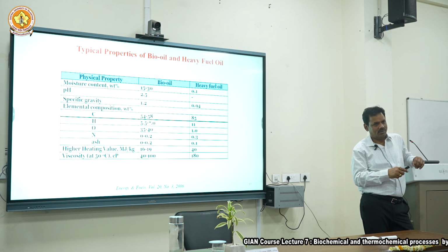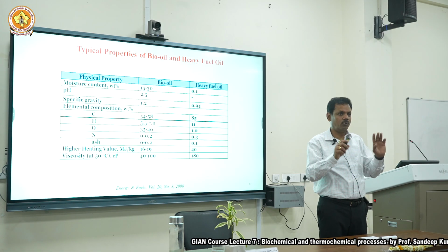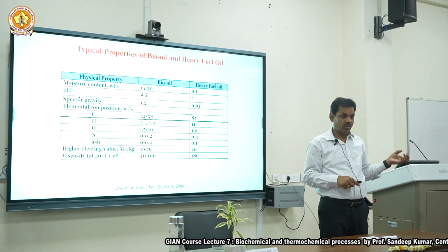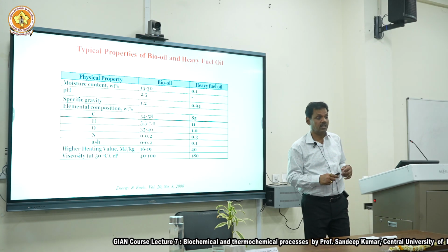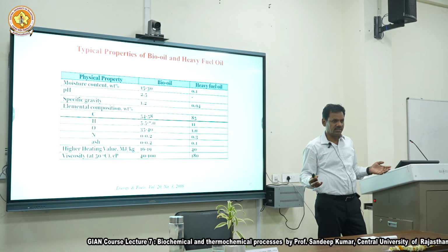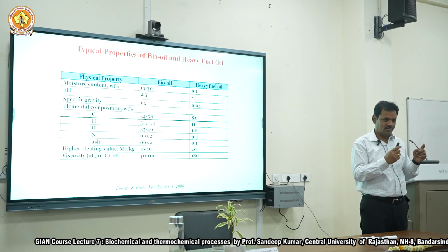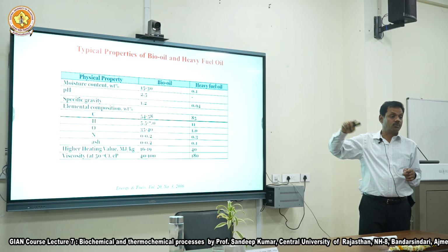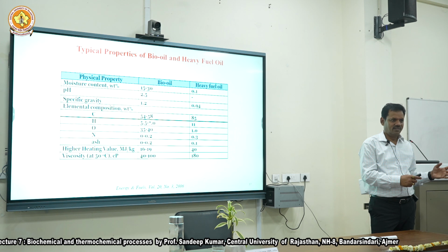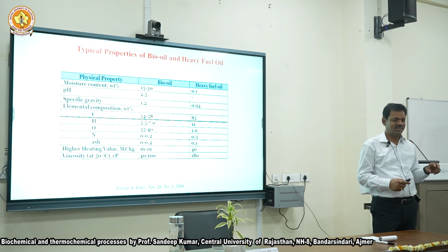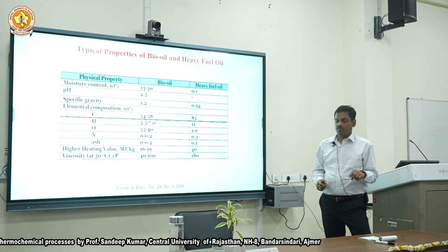Yeah, so that's fine, but take a drum and put biomass. Biomass, you know, is 15, 16 megajoule per kg, but one drum of biomass, how much energy will it have? Let's say in a drum we have 40 kg. So how much energy will it carry in a drum? Now, same drum, take this pyrolysis oil and put how much oil you can fill it. Much more energy than this. So even though the energy density per unit volume increases, per unit mass the heating value is the same.